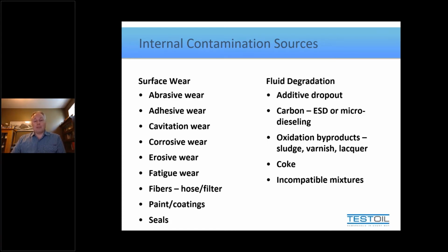The primary way that many of us may be familiar with is what we call the generation of insolubles. Now, that's not a term most of us use when we describe it, because insolubles is not something we necessarily care that much about until such time as they plate out. When the insolubles plate out on metal surfaces, we give them new names that we generally recognize quite quickly. Things like varnish, gum, tar, lacquer. So these tend to be soft particulate that don't cause any machine damage until such time as they plate out, and then they start to insulate and otherwise can help cause parts to either stop moving or have a high restriction of movement.